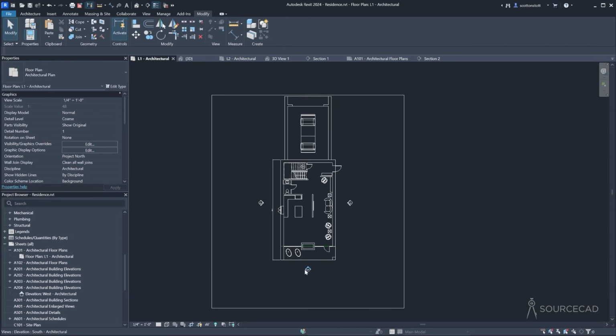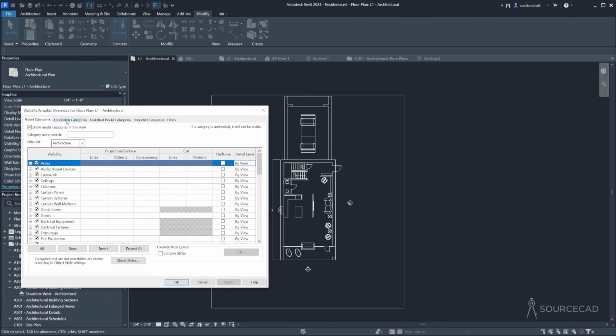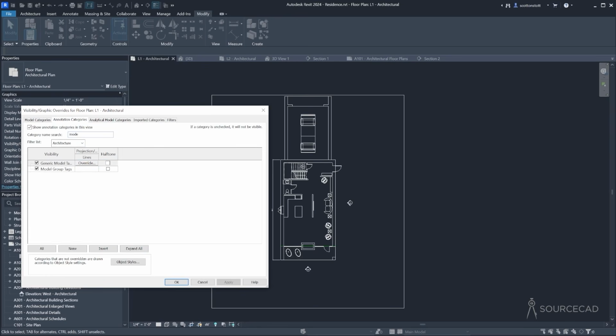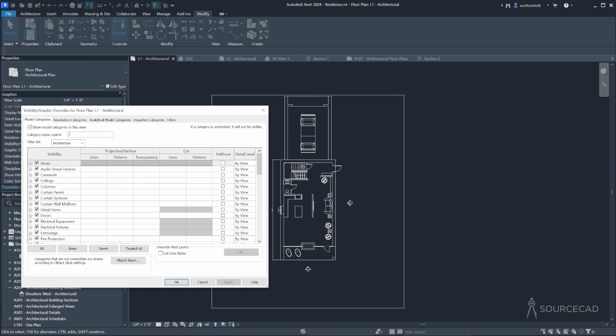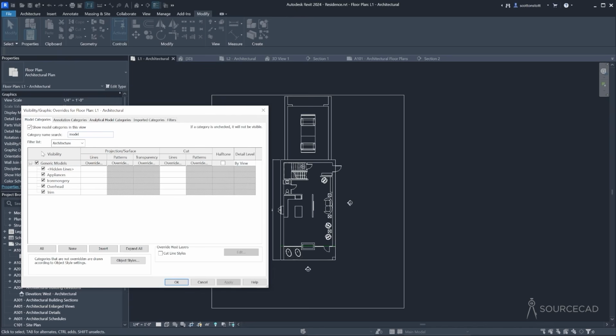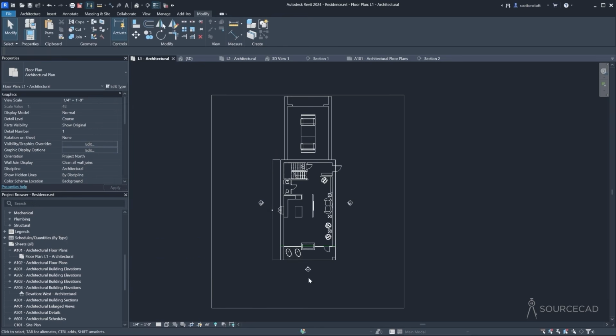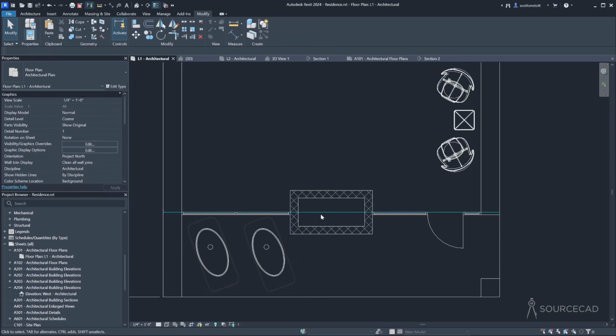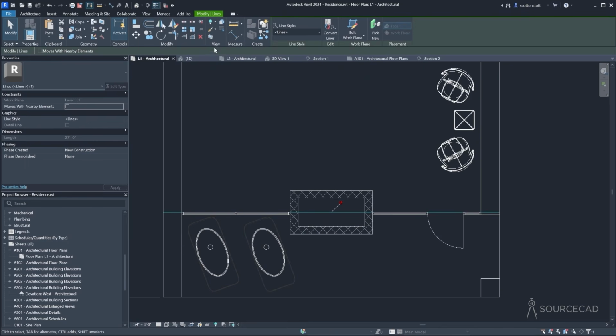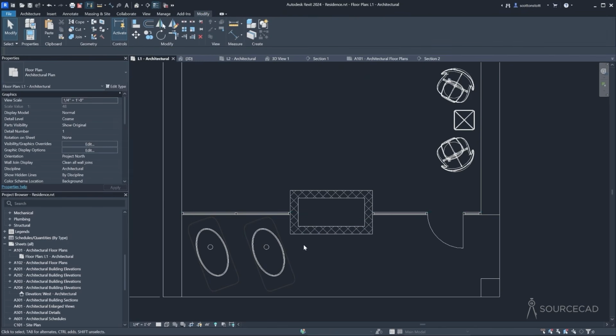I would also like to exclude model lines, like these green lines here. I don't want to see them in my plan. So I can go in here, go to annotation categories, and I can start to type in the word model line, and I can then uncheck these things. Now, I'm not seeing them here. Maybe they're not shown here. What I could do is, if I'm not seeing them directly, I can select it and then go up here to hide category, and that will do it.